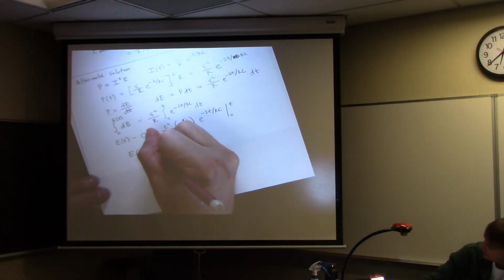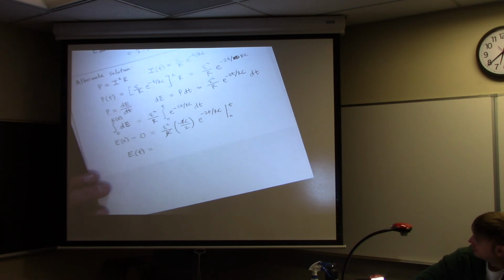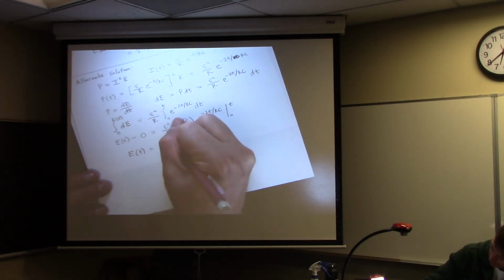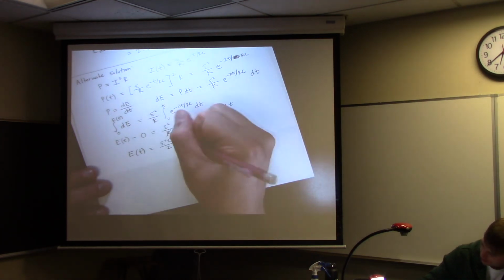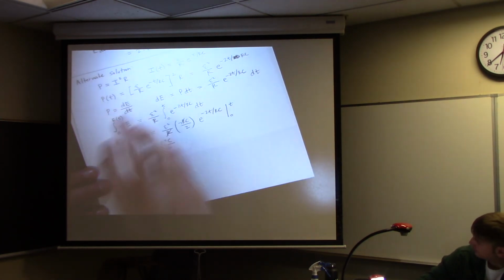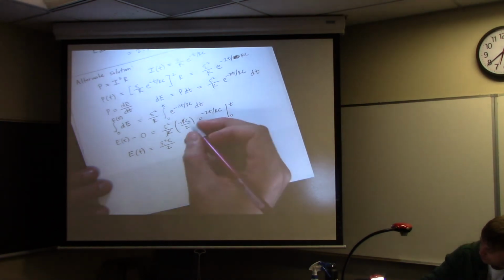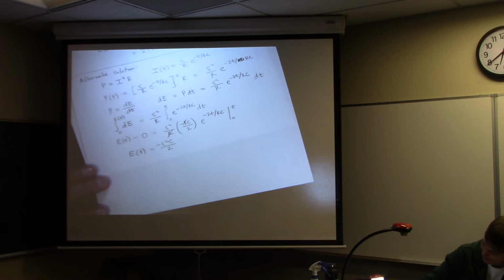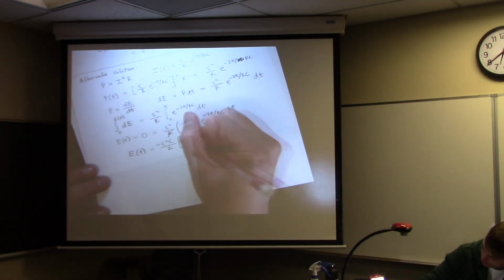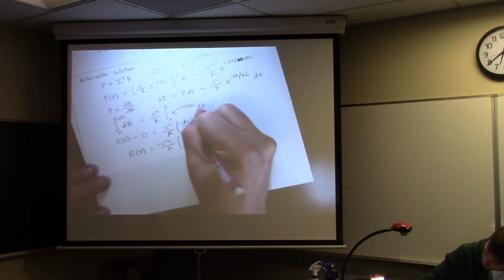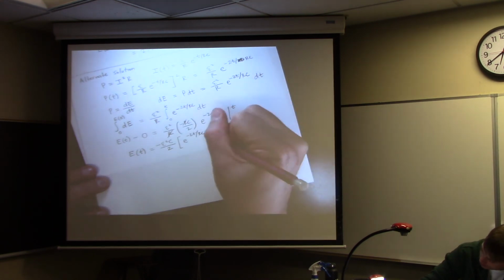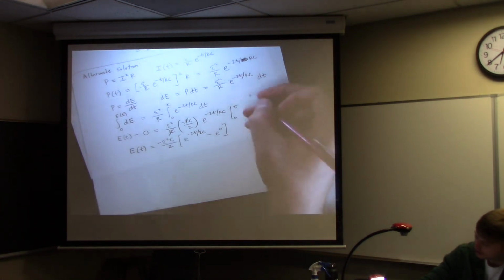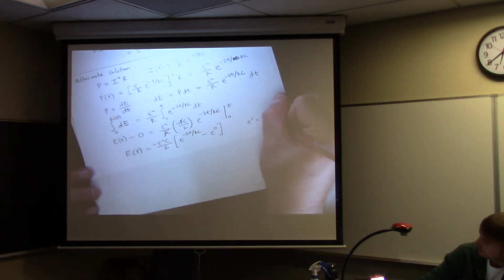So, okay, on the left side, I just have energy used at time t. Then I have epsilon squared c over 2. And then that's what the simplified factors are. Oh, I have a negative sign out there too, because there's a negative sign there. So plug in the top limit, we get e to the minus 2t over rc. Now plug in the bottom limit and you get e to the 0, which is actually 1. E to the 0 is 1.